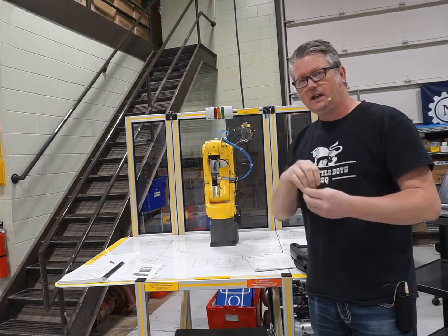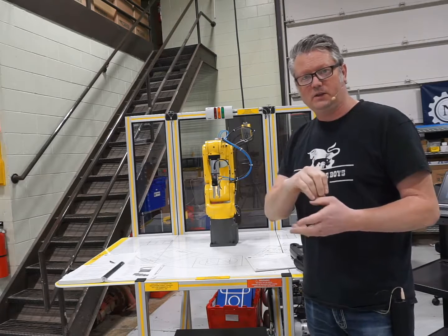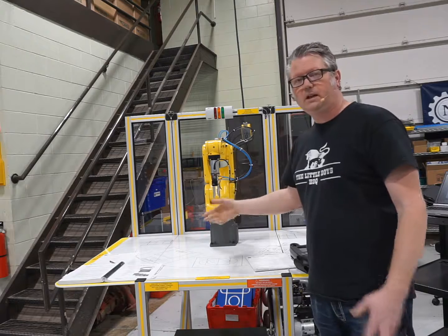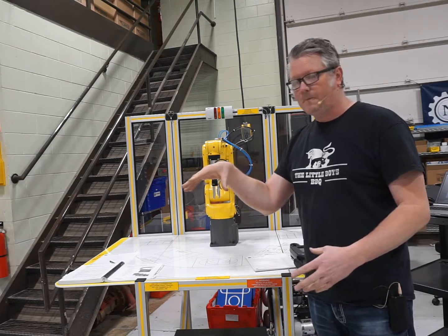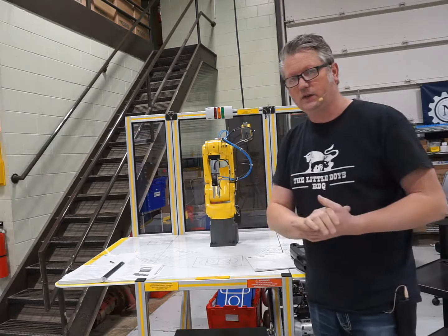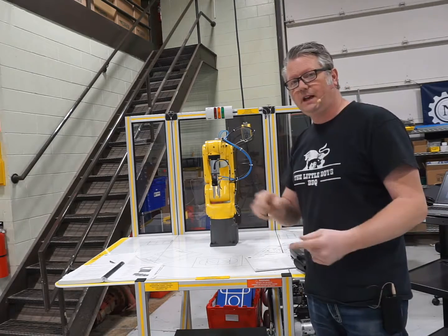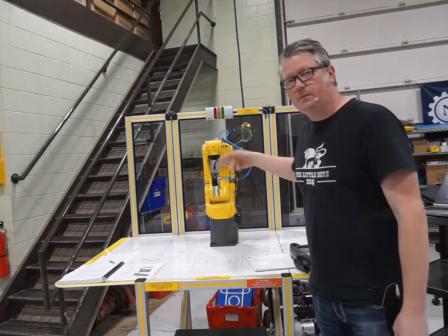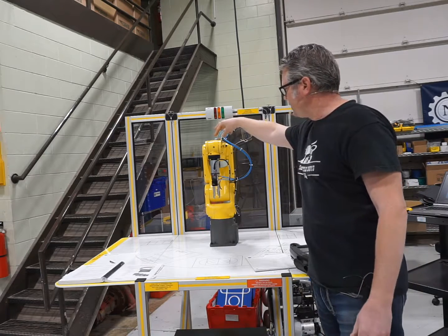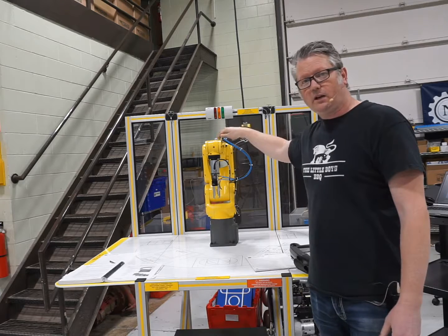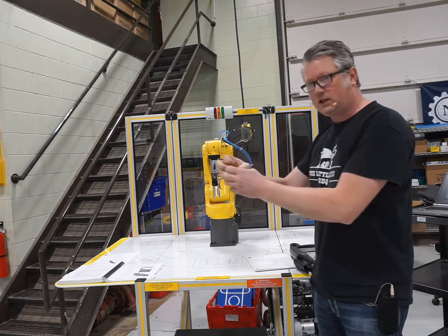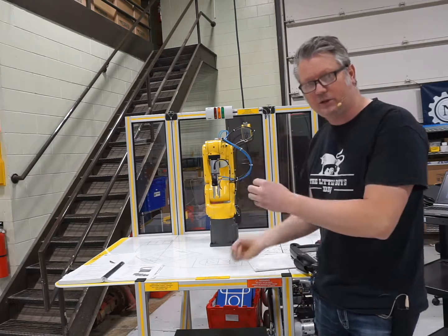We could connect a number of those pins to different sensors on the end of the tooling for the robot. So as an example, if the gripper closed and a sensor was made telling us that it is closed, we could feed that information back, and that would become a robot input. So the robot inputs and outputs are things that are physically wired up to the robot themselves, and then there's a connection that goes from the robot to the controller.